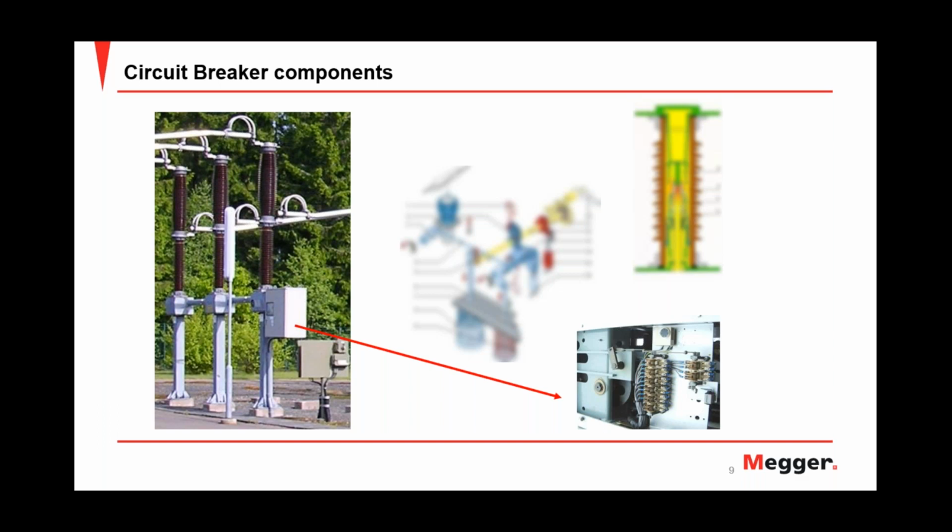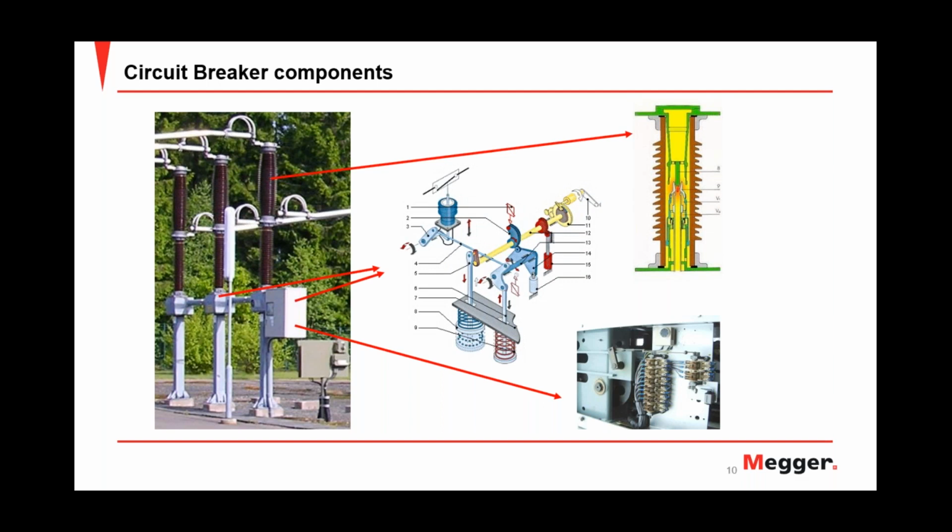As a result, some of these auxiliary contacts are by design leading or lagging the operation of the main contact, and their proper operation needs to be tested during the maintenance cycle. Now, having an overall look with all this information added, a typical circuit breaker, which looks quite simple and robust at the first look, turns out to be quite a complex part of the power system, and proper consideration must be given to how comprehensive the testing will be.